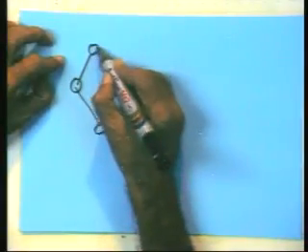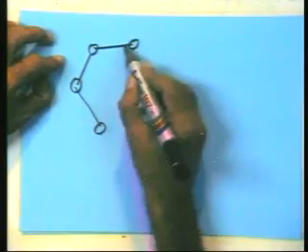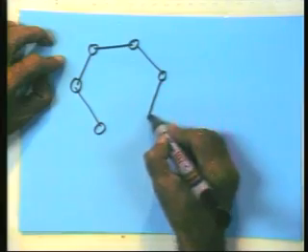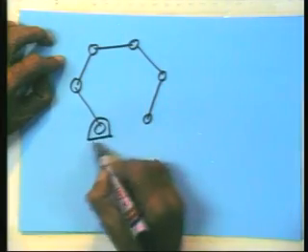You could of course have a serial. If you have a 2 degree of freedom system, when you have a 2 degree of freedom planar system, can you orient the end effector whichever way you like? In a plane we require 3 degrees of freedom, so we should go for a 3 degree of freedom closed chain. I will draw one, may not be the best in the world, but nevertheless 1, 2, 3, 4, 5 and 6.